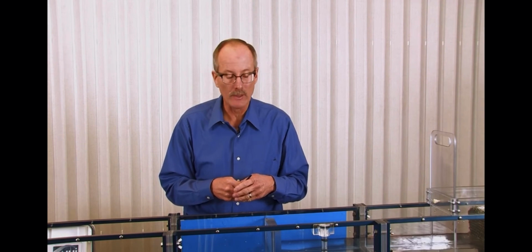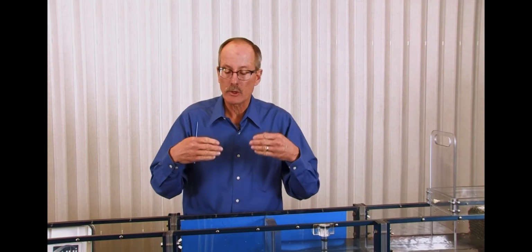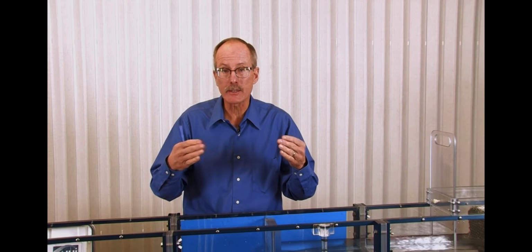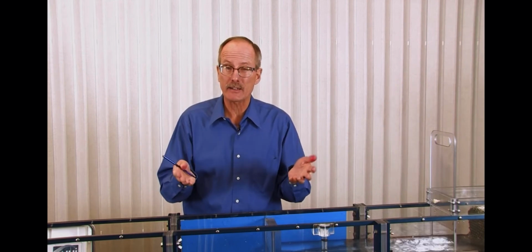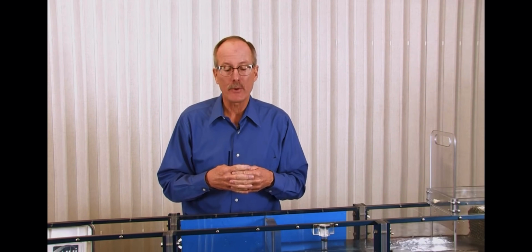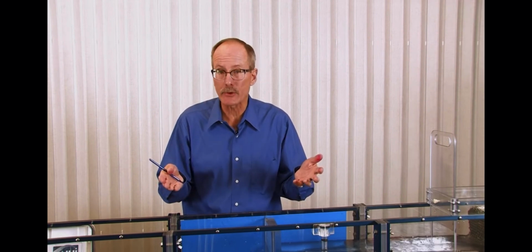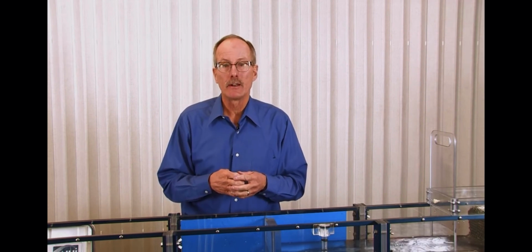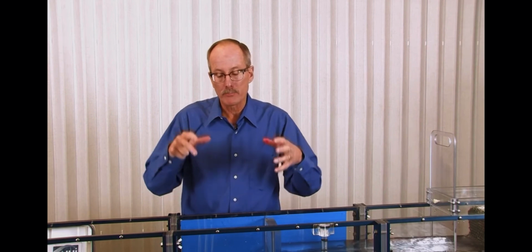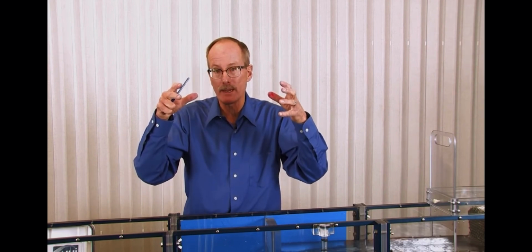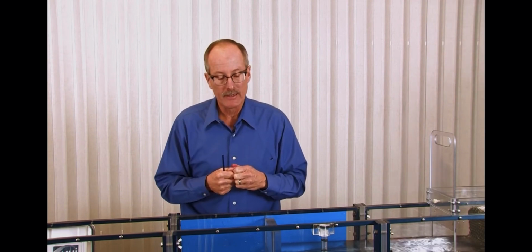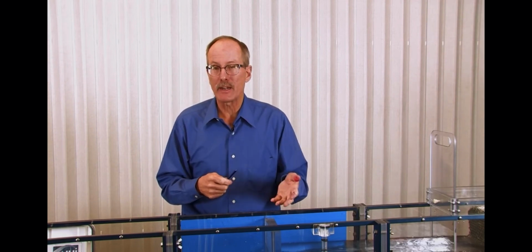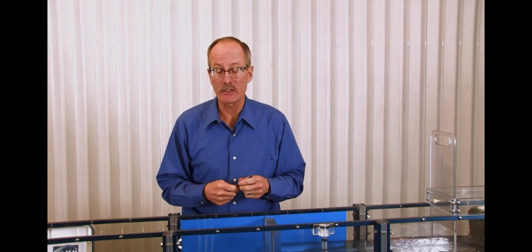So the orifice equation is an equation we use that underlies many of the calculations we do. For example, when a culvert starts to pond and we get headwater acting on the barrel, it's basically acting like an orifice. If we have a grate inlet, for example, in a sump condition, we have water ponding above that opening, and it sees that mostly as kind of a horizontal orifice. The equation underlies many of the calculations we do in highway drainage design.